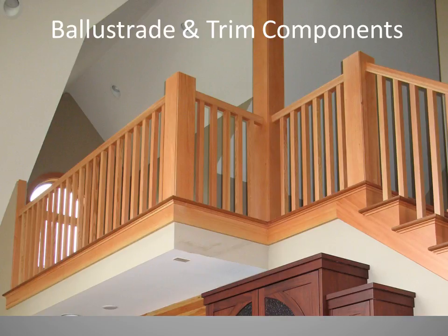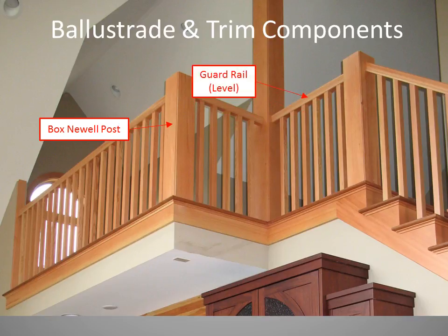Balustrade and trim components. In this application, we have a box newel post that forms a corner joint in the baluster or railing. A guardrail is a level top cap similar to a handrail, which is sloped. And we have balusters on the guardrail as well.